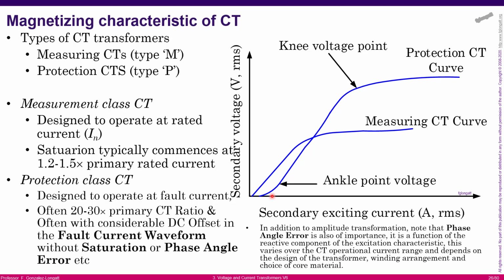Typically, when we talk about current transformers, we can identify two different types. Some current transformers are used for measurements, using, let's say, low quality magnetic material to create the magnetic core. For measurements, we need linearity between 0 and a normal overload, probably 1.2 or 1.5 times the rated current. Then if the current goes to full fault current, we use the saturation of the secondary exciting curve in order to avoid the destruction of the measurement device.